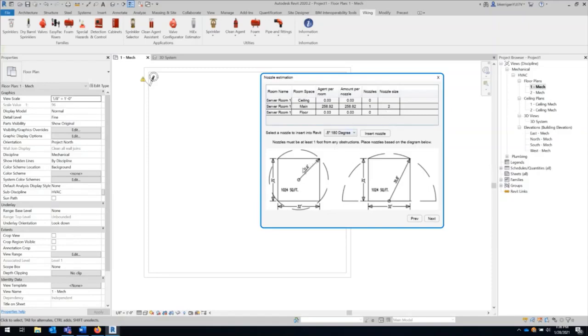At the bottom, you'll see some basic diagrams indicating the coverage area. So our nozzles come in 180-degree variants and 360-degree variants. They actually cover the same square foot footprint, be it the 180 or the 360, where the 180 obviously has a longer throw. So in many scenarios, you can actually get shorter pipe runs and an equivalent area of coverage out of the 180-degree nozzles. So that's always interesting to keep in mind. So I'll just use a 360-degree nozzle, just so people are maybe a little more familiar with that. It's a bit more sprinkler-like, in terms of just a normal pendant or upright sprinkler.